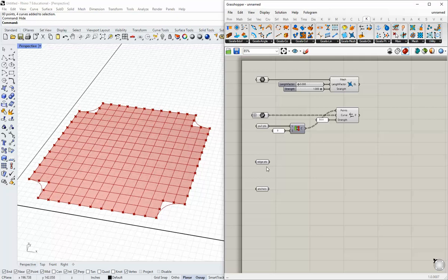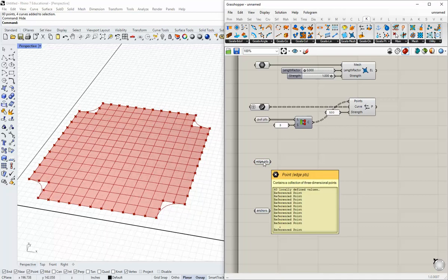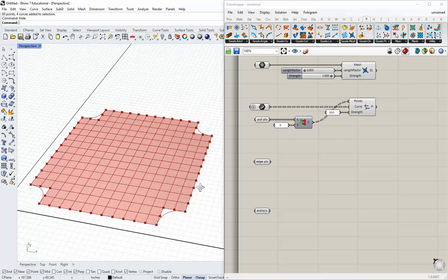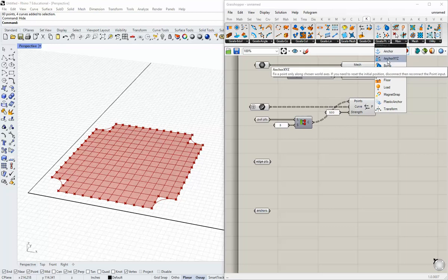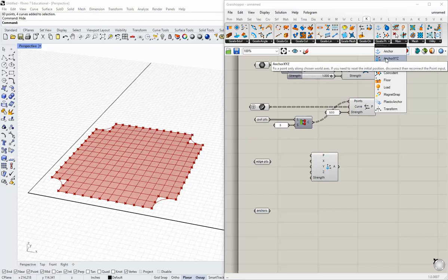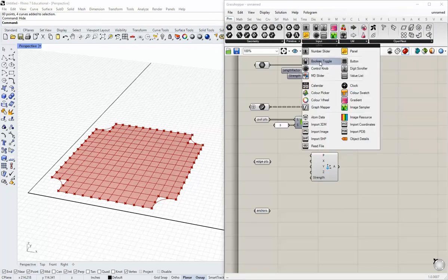All right. With our edge points now, to get the form started, what I'd like to do is constrain their movement only in the Z direction. I'd like this dome-like form to have edges that are orthogonal. So we'll head over here into Goals Point, and the Anchor XYZ component. There's a couple different anchors here. You're going to look for the second one down, XYZ, because this one's going to give us some ability to constrict movement in any of those three directions.